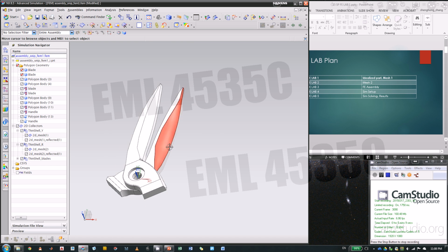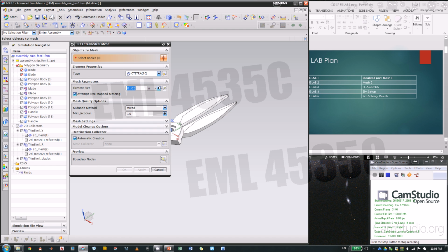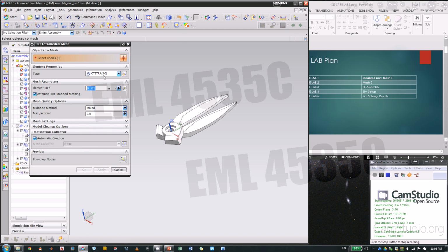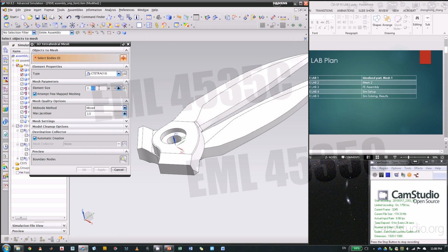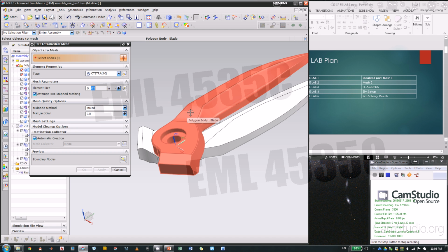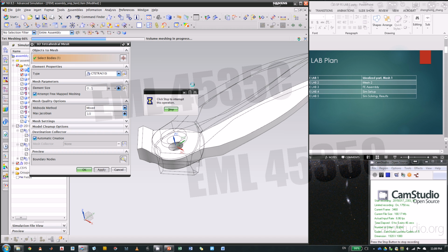This is really simple. You basically just need to do a 3D texture. Here we use texture 10. It's a parabolic texture, so it will not be too stiff. And the size is different. The size is 0.1 inch for the 3D texture. Again, that's 0.1 inch. That will be written in the slides, which I don't have now. So 0.1 inch and texture 10. Let's get one first.